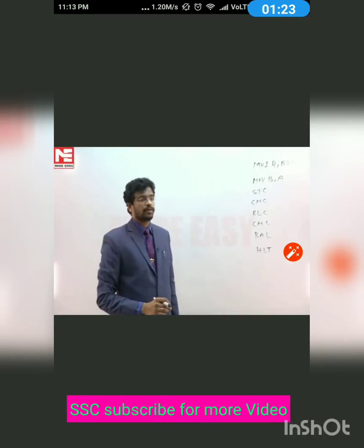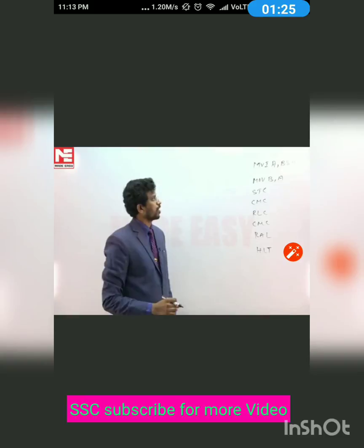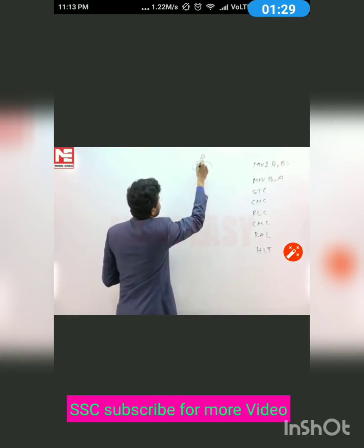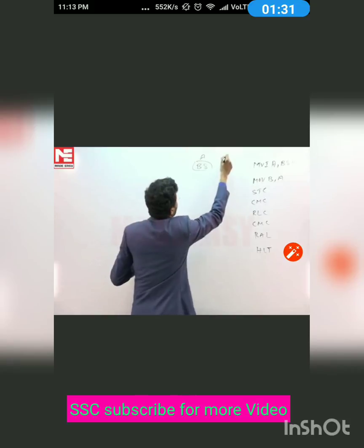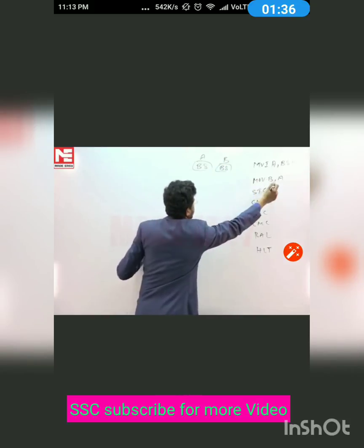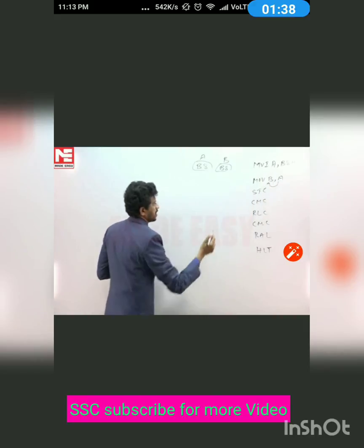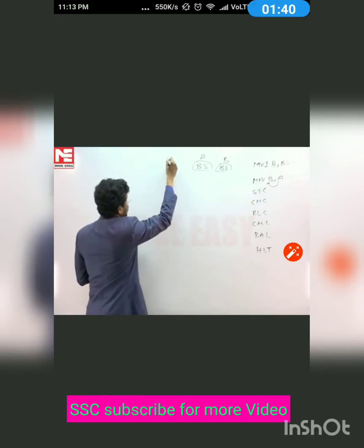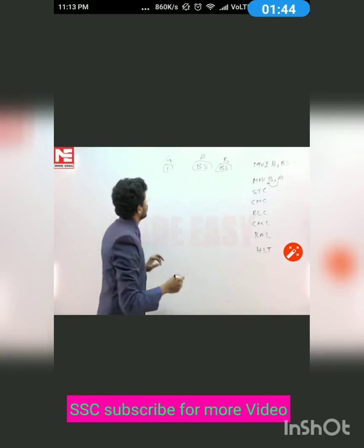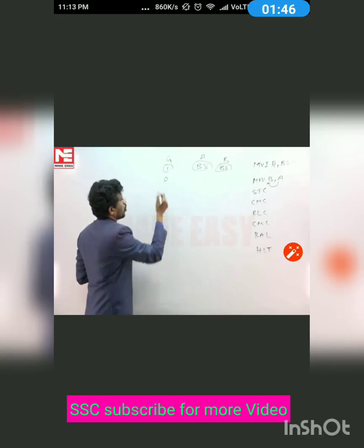Let us see the content of the accumulator after the execution of the program. The given information is move immediate accumulator with B8. The content of A is copied to B, that is B8 is copied to B. STC stands for set carry, and hence the carry flag is 1. After that, CMC, complement carry, the carry flag has become 0.